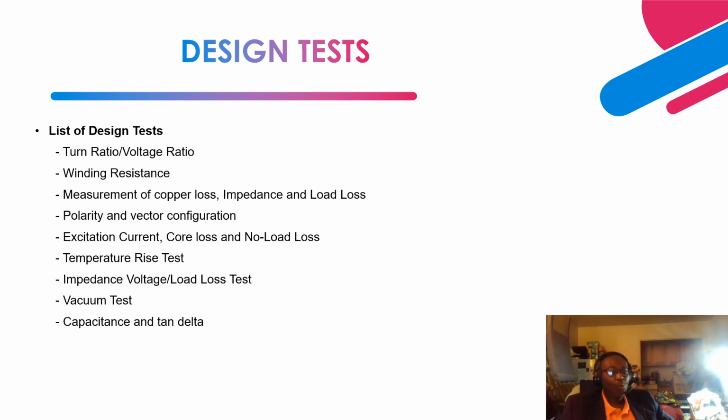All these capacitances are formed because of the insulation arrangement, the paper and the oil. Right? So you measure this capacitance to indicate the winding arrangement. So that becomes like a fingerprint, a baseline for this transformer throughout the whole operating history of the transformer. So in the future, let's say during site acceptance testing, or in the future during the operation of the transformer, when a routine test is performed, you compare this capacitance testing with the factory acceptance testing to identify any internal active component shift of the transformer or the winding arrangement shifts.